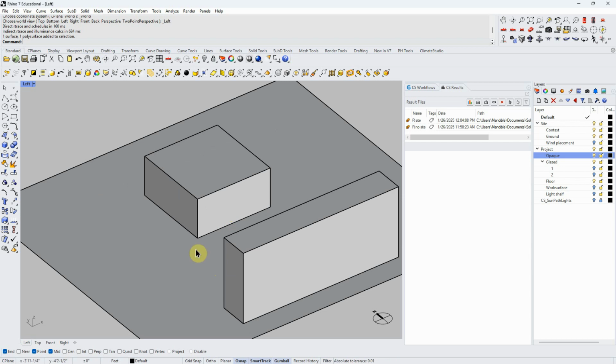But the point is now that we're going inside the building, we're going to look at the amount of light hitting surfaces. That's different than heat. And so the measurement is not going to be kilobtus per square foot or kilowatt hours per square meter. It's going to be lux. And lux is a unit that is calibrated to how our eyes see light.